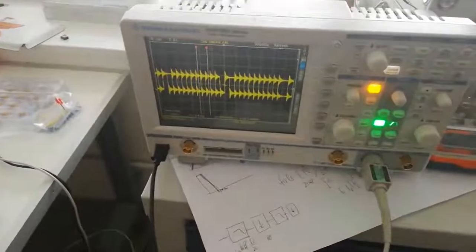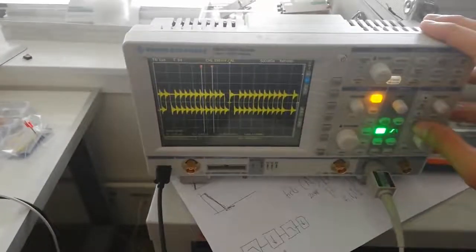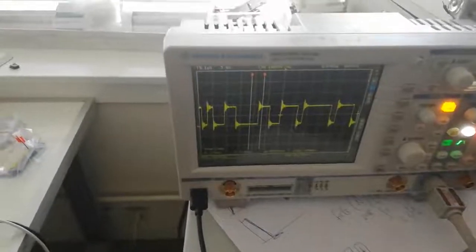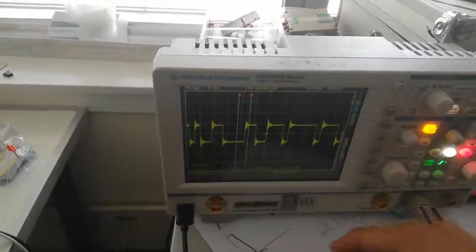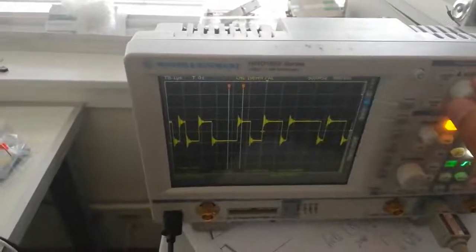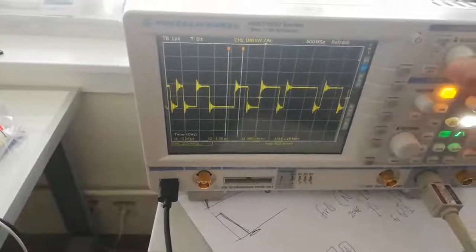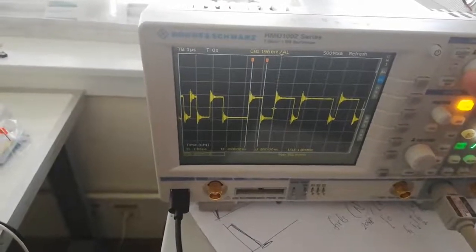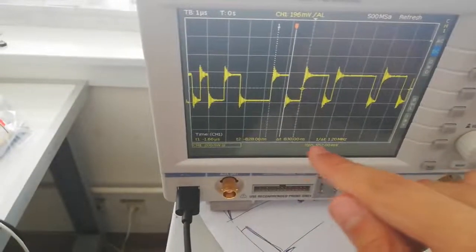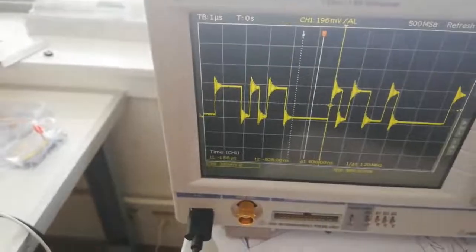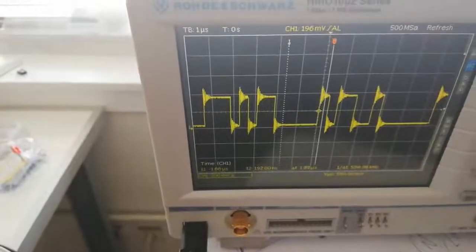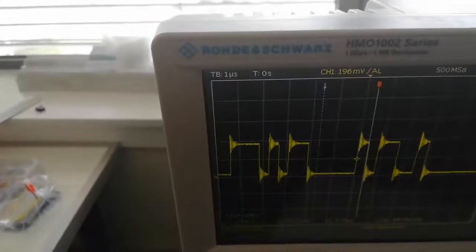On the oscilloscope, we get a nice noise. If we just run a single time, we see this. So now the question is: is the frequency of the pseudo-random noise equal to 2.5 megahertz, just as intended? To do so, we just read here to see if the frequency is right. Oh no, this wasn't the smallest interval you could have. The smallest interval you could have is here.